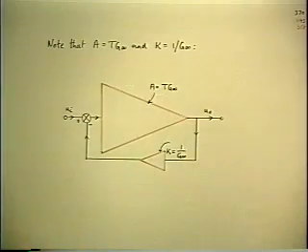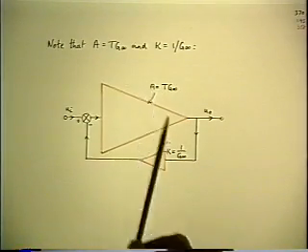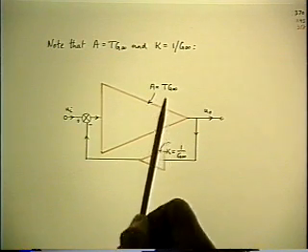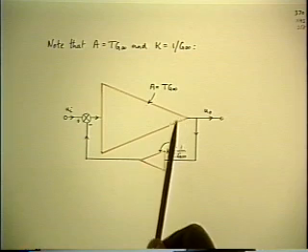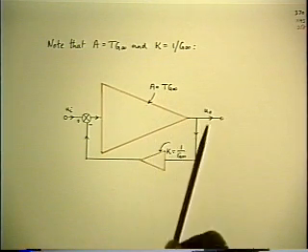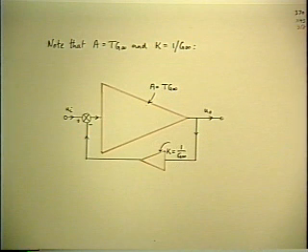Once you've calculated something to do with the LC filter and you've identified useful quantities for the answer, namely corner frequency, characteristic resistance, and Q factor, when we want to calculate something else to do with the filter, it saves a lot of work if you rewrite the element values directly in terms of the quantities you want in the answer. Let's do the same thing here. We don't want A anymore, we don't want K. So let's invert the definitions and write the forward amplifier gain as T times G infinity and the feedback path as 1 over G infinity, simply substituting the right quantities right from the start.